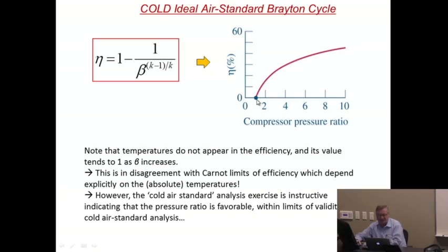The first bizarre thing is that there is no temperature in this. It would mean that you could design your turbines just with pressure ratios alone, ignoring temperatures. That is unphysical because, of course, Carnot tells you that the most important thing in a thermodynamic cycle is the ratio between the higher temperature and the lowest temperature, which doesn't seem to enter this equation, so that's strange.